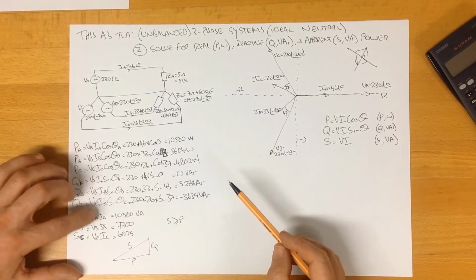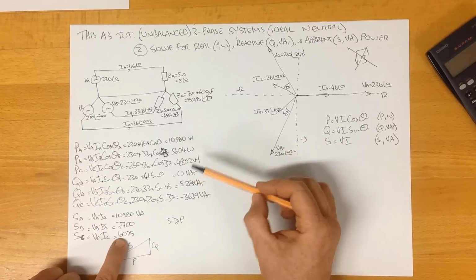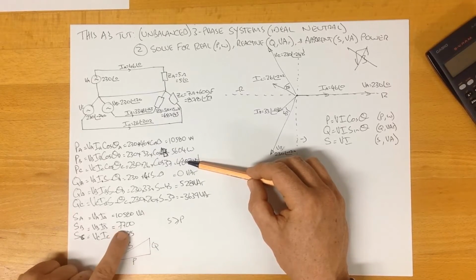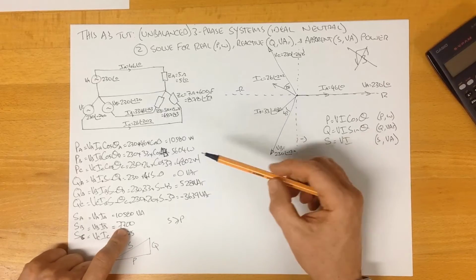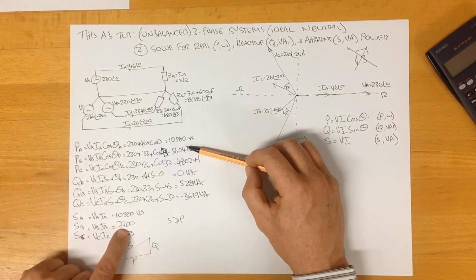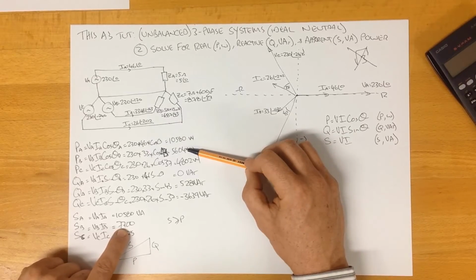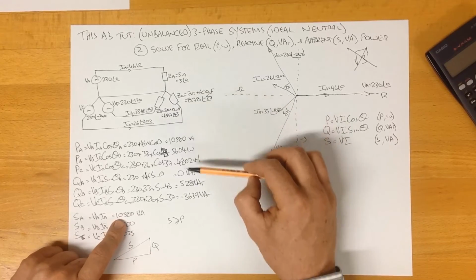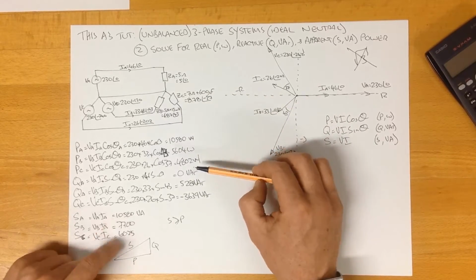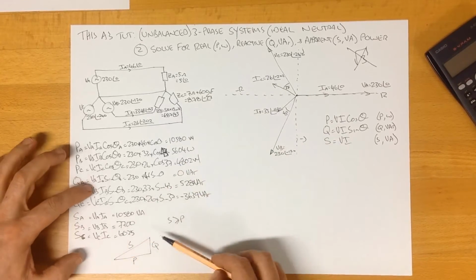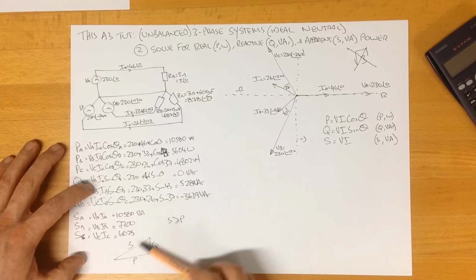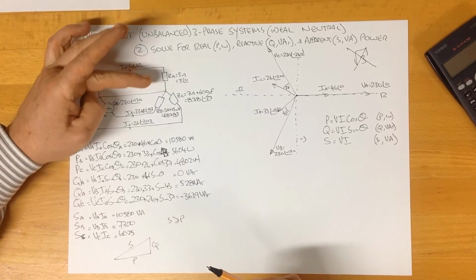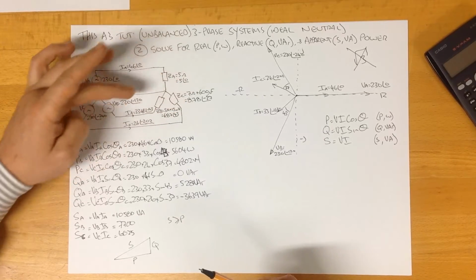So we can have a quick check. SC is 6,025, PC is 4,802. That is larger than that. Okay, good, makes sense. Phase B, 7,700 versus 5,604. Yep, that makes sense, that's bigger than that. Phase A, 10,580, 10,580. They're the same, not surprising, because Q is 0. So all of our calculations have passed this little test to make sure everything's looking okay. We now have calculated the real power, the reactive power and the apparent power dissipated in all three of these phases.